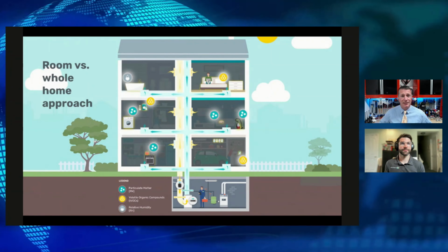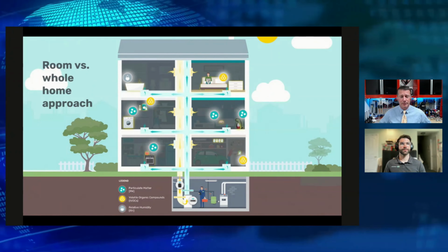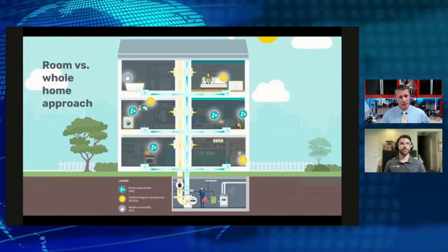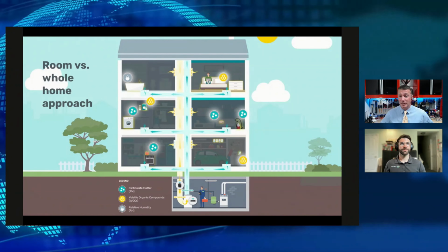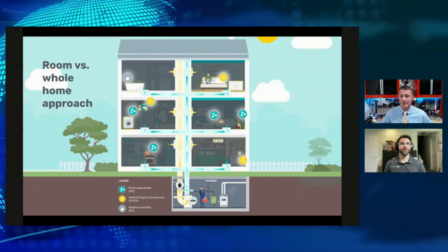Absolutely. And we had a humidifier installed and it's been 12 months and all of a sudden we're starting to have a lack of humidity and an increase of debris on filters. Oh, yeah, we got a bad humidifier pad in there. We can actually see some of those items as we're collecting data.